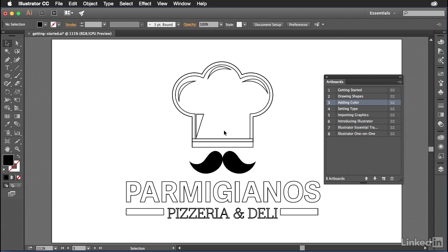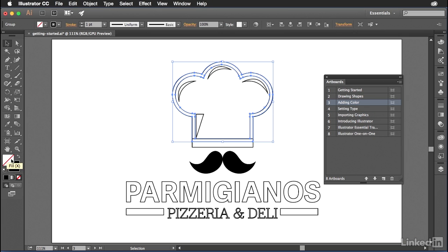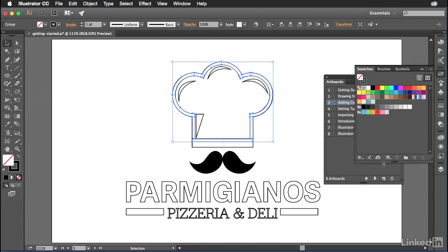Now let's do the same thing up here. Let's grab the outer portion of the hat. And if we flip-flop again, what happens? Ooh, it turns into that. So here's what we're going to do. We're going to undo that and we're going to give it a color. So how do we give it a color? Well, we target the fill first, then go over here to the swatches panel. And in the swatches panel, we can find a color, something kind of like that. There you go. You get the idea.